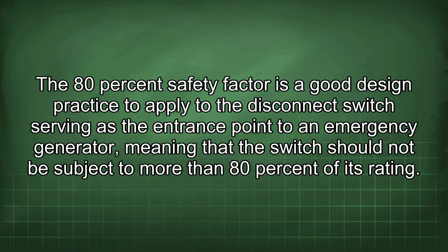The 80% safety factor is a good design practice to apply to the disconnect switch serving as the entrance point to an emergency generator, meaning that the switch should not be subject to more than 80% of its rating.